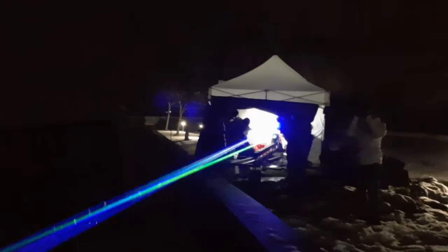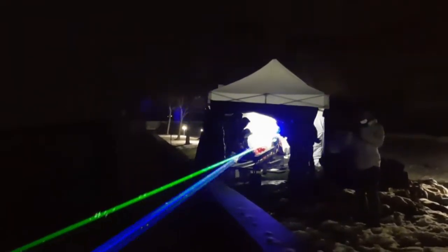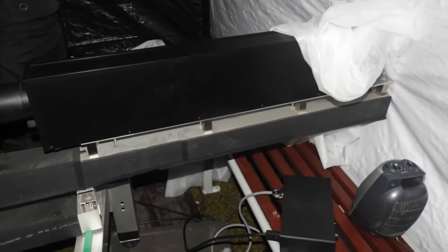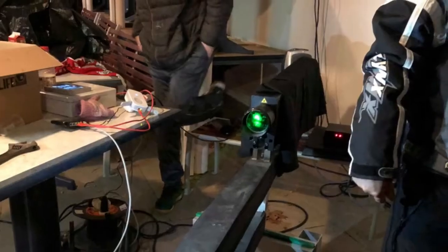The custom-built laser required a minimum air temperature of 10 degrees Celsius or 50 Fahrenheit for operation. The laser began to malfunction due to the outside temperature hovering around 3 degrees Celsius or 37 Fahrenheit. So a small electric heater was placed near the laser cooling fan intake. The warm air over the cold laser cracked the crystal in front of the laser diode, which caused the beam to be distorted and the focus malfunctioned.